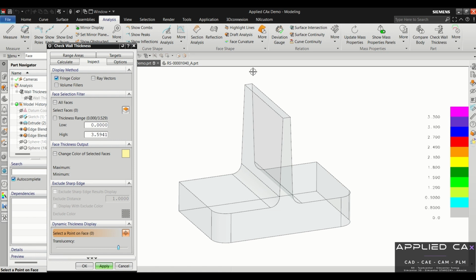So to give you a little more understanding of that, we have this example part. As I move my cursor around in this object here, you can see that the balloon or the sphere actually changes sizes as the walls change in thickness in those locations. If I stop at this location here, you can see that it'll give you a value for the thickness, which correlates to the chart over to the right. As we move down to here, the default thickness of this part was 3 millimeters, and it shows up as 3 millimeters as the thickness there.